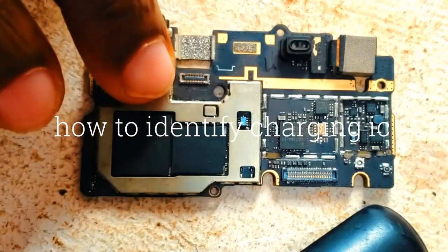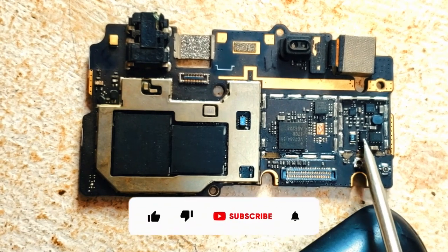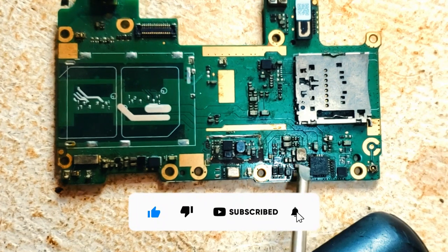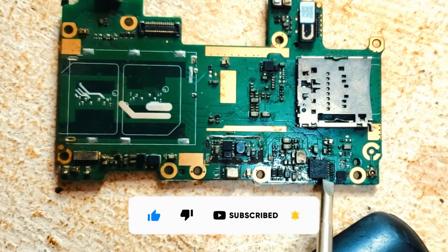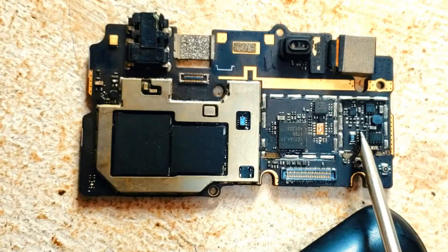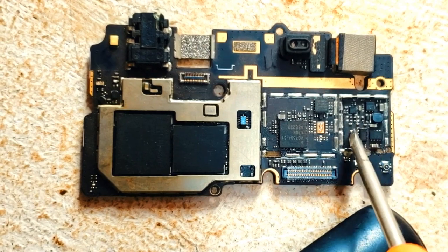How to identify charging IC? Mobile charging IC is found in the power section of a mobile. In most phones it is similar to the power IC. It has one or two big coils with a few capacitors around it, but not as many as the power IC. Here is the easiest way to identify charging IC: the IC beside our 22 resistor is the charging IC.